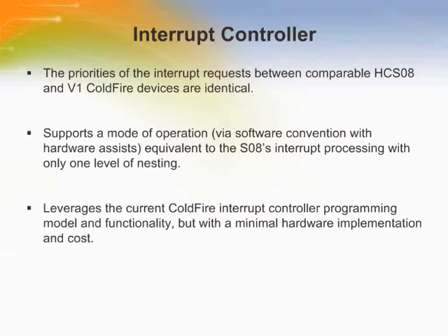The interrupt controller is intended for use in low-cost microcontroller designs using the version 1 ColdFire processor core. In keeping with the general philosophy for devices based on this low-end 32-bit microcontroller, the interrupt controller generally supports less programmability compared to similar modules in other ColdFire microcontrollers and embedded microprocessors. However, this interrupt controller provides the required functionality with minimum silicon cost.